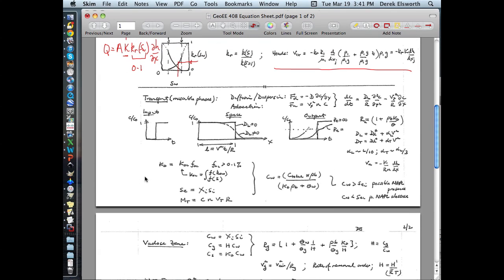We also talked about transport. We talked about advection dispersion equations. We talked about them again today. We basically made the case that if you look at behavior in terms of an equivalent dispersion and an equivalent advective velocity, where you divide just by the retardation coefficient, if you use those equivalent parameters, you can use any of the graphs or concepts that we looked at from Fetter. And those would correspond to, we always define them in terms of an upstream input function, what it would look like in the core, and what it would look like at the downstream reservoir in terms of arrival times.